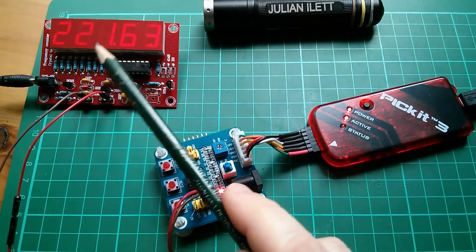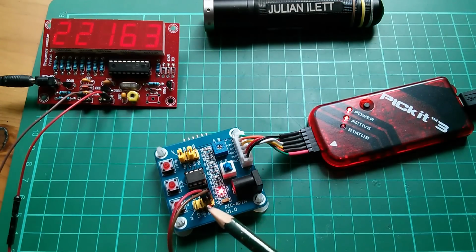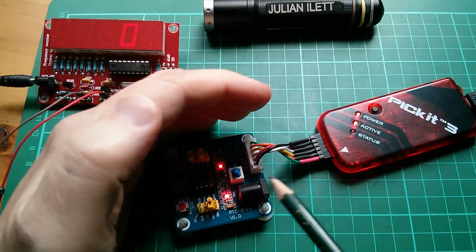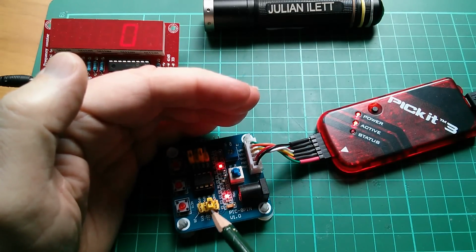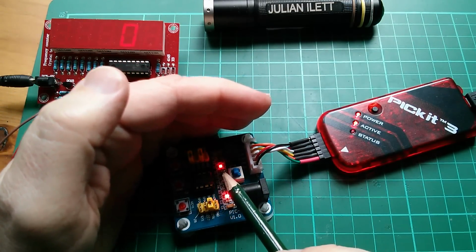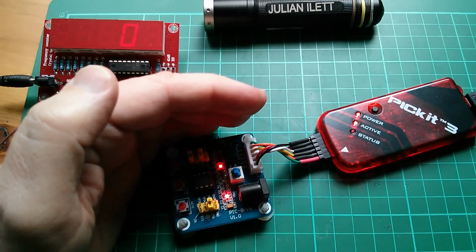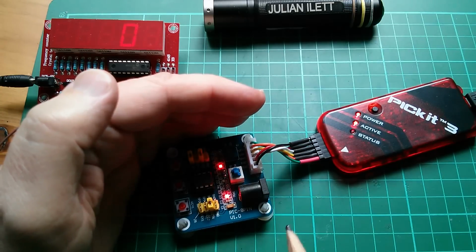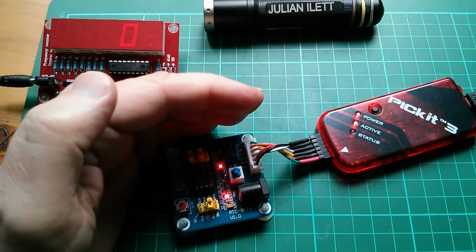Yes, it's working. That's oscillating now on the LED output at 221 kilohertz. And with the frequency counter disconnected and the LED reconnected to GP0, yes, we've got that dim LED because it's running at 220 kilohertz. How do I make this flash in the remaining few seconds before I get fired?